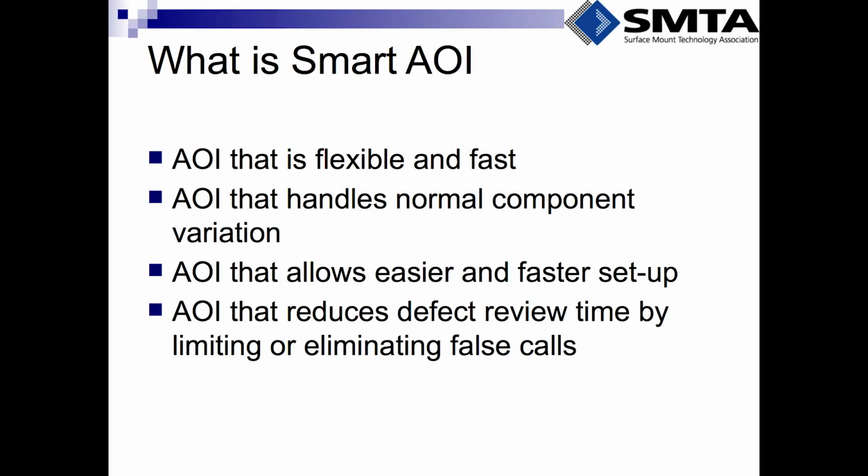Traditional AOI systems, I don't think anybody is really a fan of, because they're hard to program, they take a lot of data, they take tuning, they take someone who is spending a lot of time with them, and generally what they turn out being is someone who is passing on the defects, or passing on the passes and pulling out the defects. So you've got a lot of operator intervention. That's traditional AOI, and that's why people don't traditionally like AOI, is because it's labor intensive.